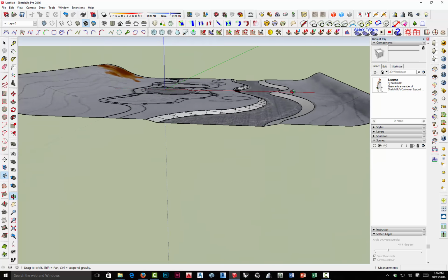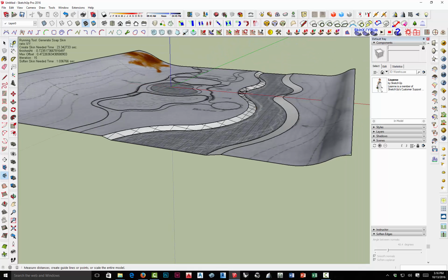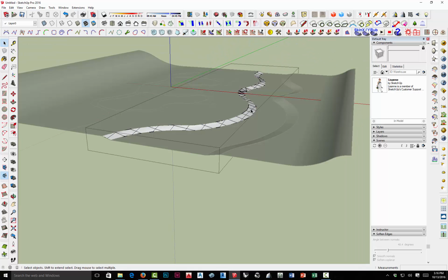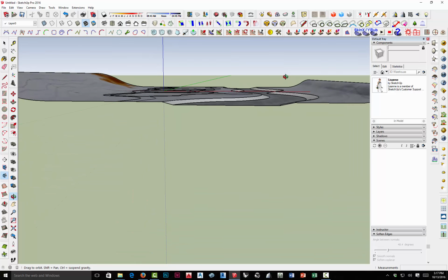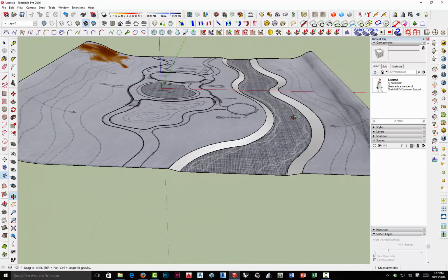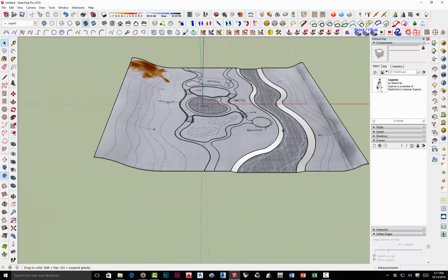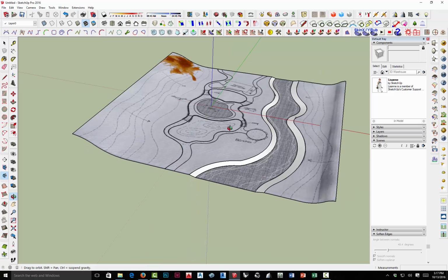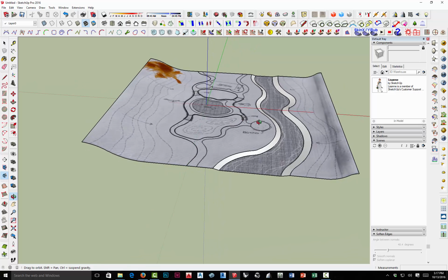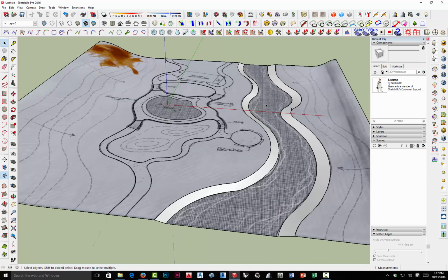All right, so there we go. My select tool, open the group up, triple click, soften smooth, back out of there, and we're ready to go. Okay, that's really the steps I went through this morning in order to create these basic forms.